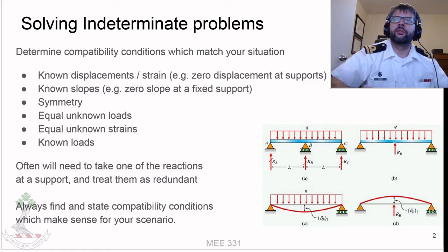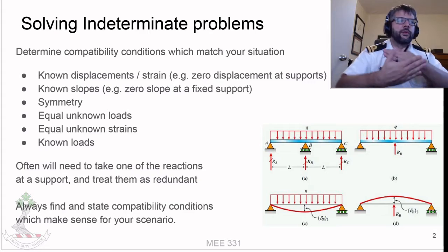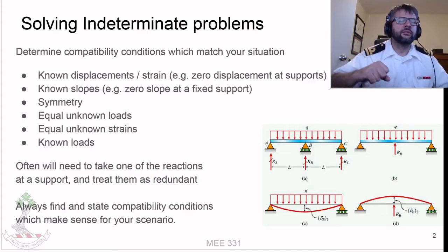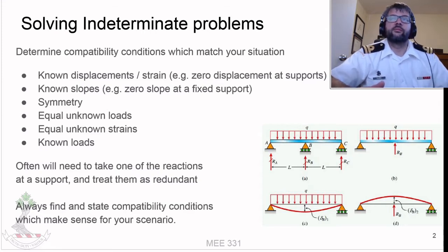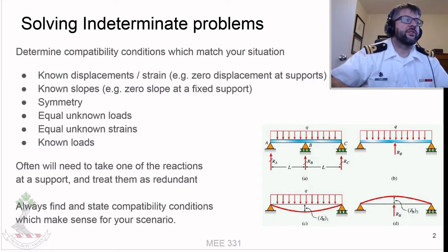But if we make use of symmetry, then since everything is symmetrical about those two axes, we know that the reaction forces at each of the legs of the table are going to be equal. Therefore, we can just assume that the reaction there is equal to the weight of the weight plus the weight of the table divided by 4.